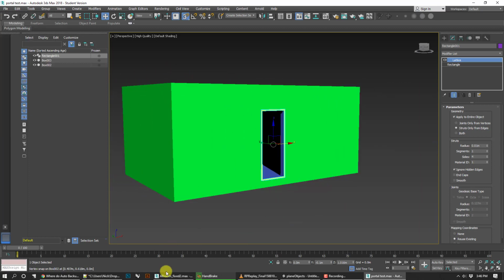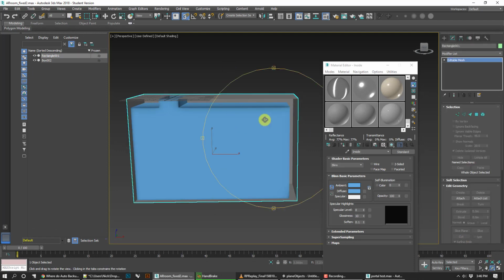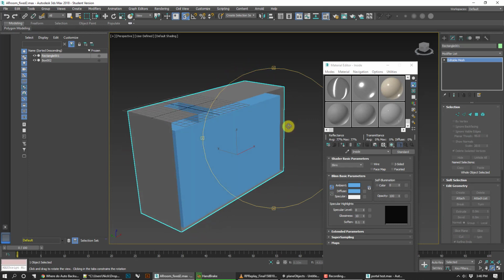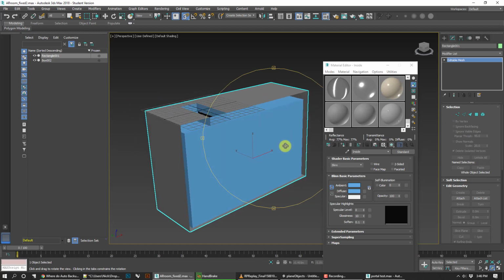And one more thing too. This is the actual file that I used. You can see I actually got rid of the floor on the outside wrapper. I would go ahead and rotate that. You want to rotate it negative 90 degrees in the X because of the way Unity imports things. It's just going to make it work better when you do the import. And the same thing with the frame.